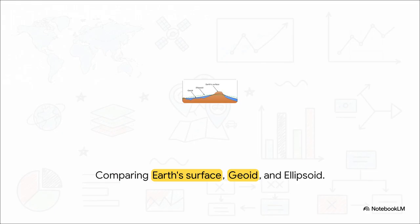Notice the visual contrast between these three fundamental surfaces. First, you've got the physical Earth's surface, the actual mountains and valleys you stand on. Then below that, the blue line represents the geoid. This is a highly complex surface based purely on equal gravitational attraction. It's essentially where the ocean level would sit. Finally, that dashed green line is the ellipsoid. This is a smooth, mathematical model of the Earth's shape that our computers can actually calculate to establish coordinates.